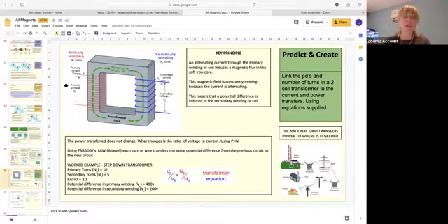From a power station, the power coming out of a power station does not change, okay? Remember, power equals current times voltage, or voltage times current. Power doesn't change coming out of here. All the power that is leaving my power station is going to come round into my homes, hopefully not losing any through resistance on the way, or heat loss and things like that, very minimal, and we always assume 100% here, okay? So what changes is the voltage, the ratio of voltage to current, okay?